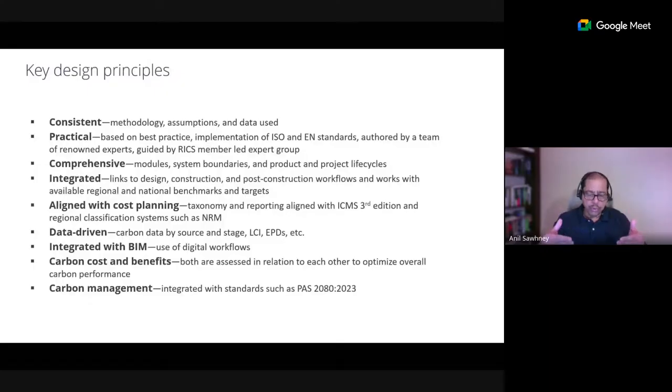Okay. With WLCA, you don't just need to look at the first cost. You can actually look at the life cycle cost and the life cycle emissions. So maybe one of your options is high on embodied carbon, but low on operational carbon. So there is a trade-off. The other one is low on embodied carbon, but perhaps very high in operational carbon. So you can see the cost and benefits of their design choices, material choices, product choices also.